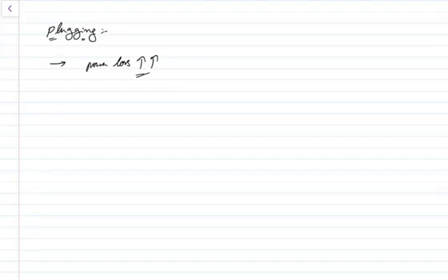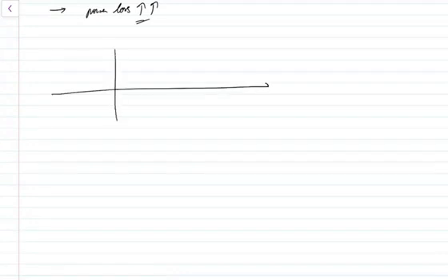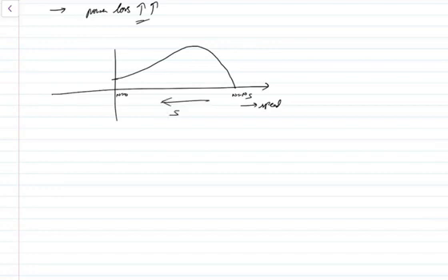So we have already known the torque slip characteristics of an induction motor. So if I am drawing this like you have studied in this way, so if this is my value of the speed, the torque slip characteristics, the torque will vary like this. So it will reach the peak, then it will get down at speed n is equal to ns. So this is at n is equal to 0. Or this can be written in another way. This is my slip. So at this point the slip is equal to 0. At this point slip is equal to 1.